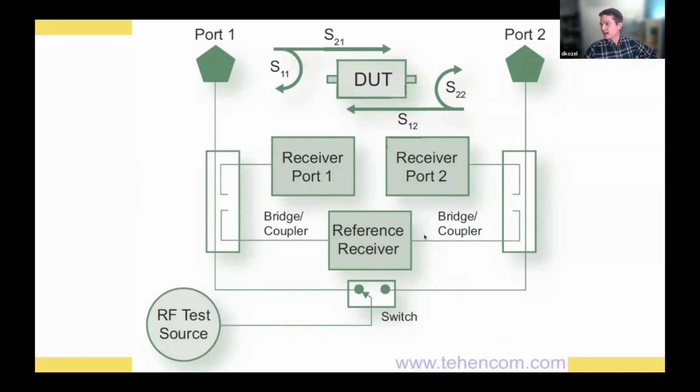We've got our S11. On the NanoVNA, we can measure only the power coming back into port 2. So we can get this S21 parameter coming back across and into port 2. And so this is what we call a kind of 1.5 port VNA. And if you have a NanoVNA yourself, you can look on the front. I'm sure this won't show up at all, either through my camera blur or through the screen, but you'll see that it actually has the labels on it.